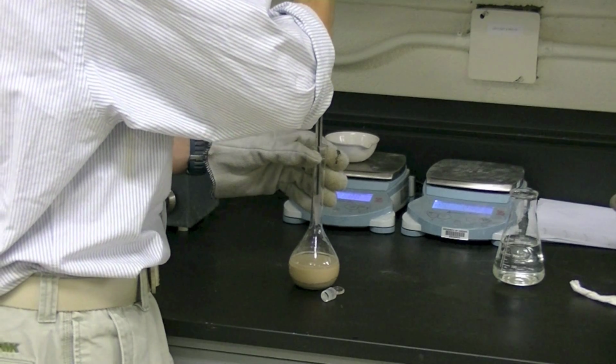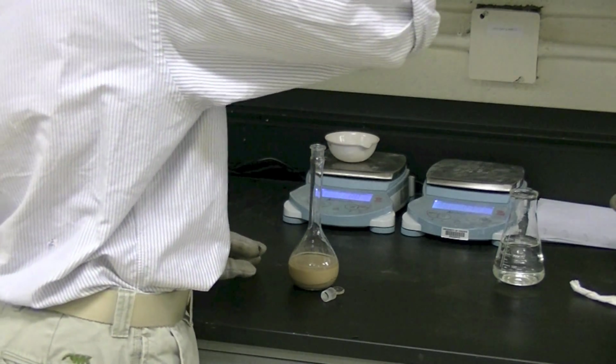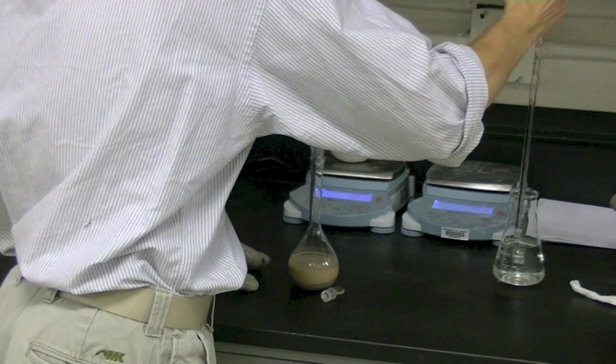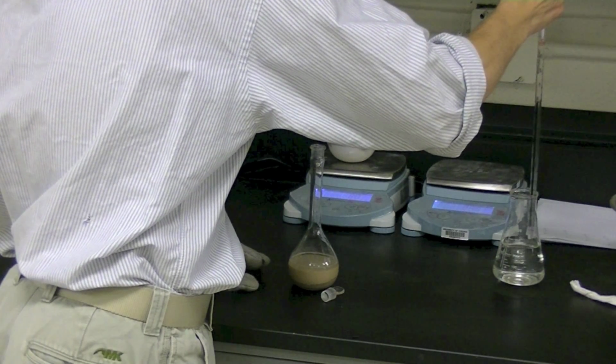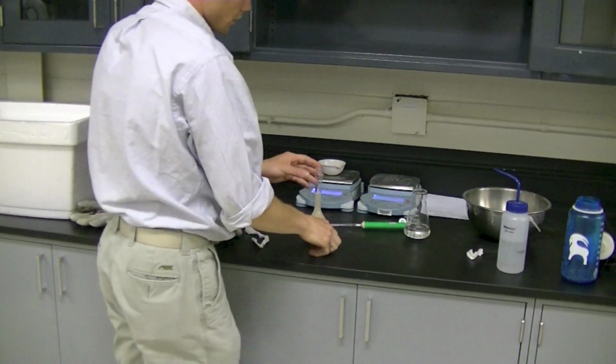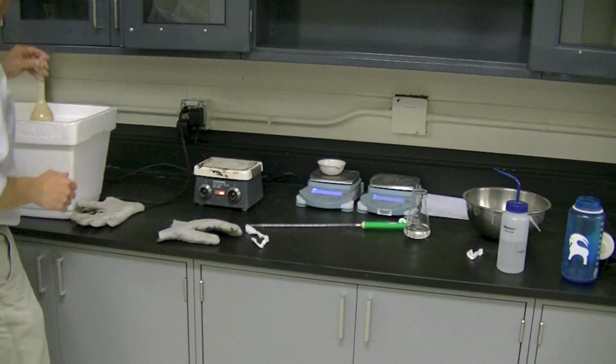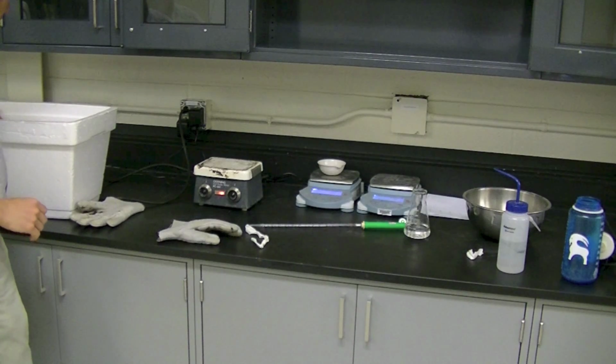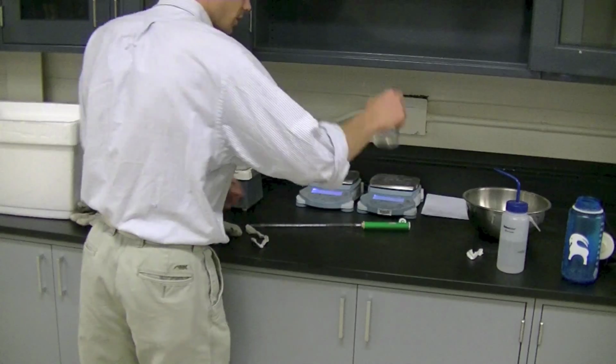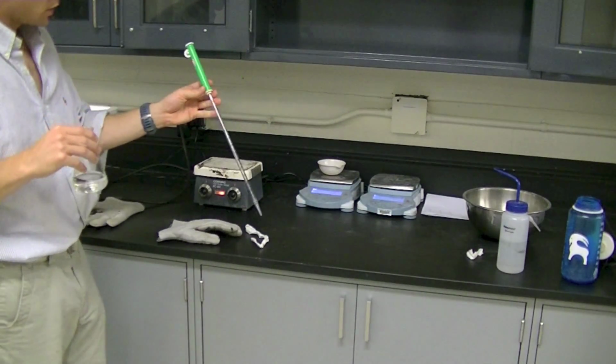Move the tip up as the water level rises. Increase the flow rate slowly as the water level rises. Again, fill to just below the calibration mark. Put the pycnometer in an insulated container with extra deaired water, a thermometer, and a pipette or an eyedropper. Allow thermal equilibrium to occur overnight.